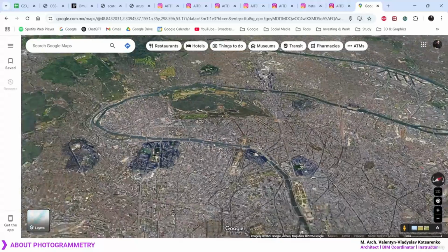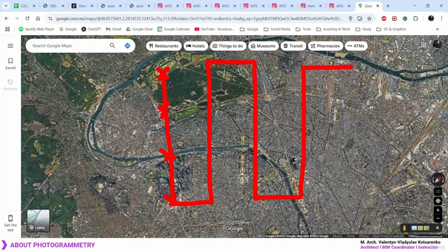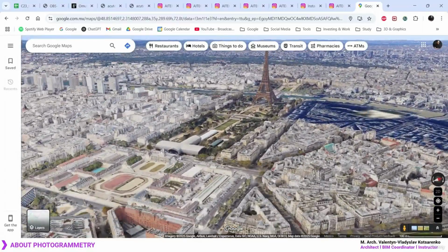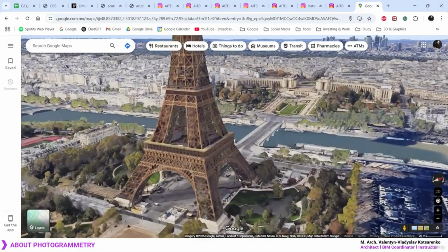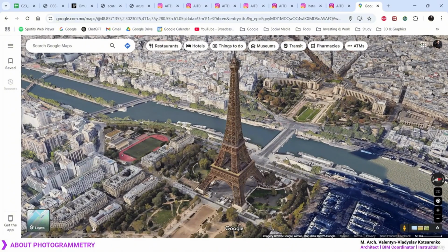So what's going to happen is that a plane is going to create a flyby, okay? It's going to use satellite photos and information created with the flyby of a plane in zigzag. It's going to take multiple photos, and then the photos are going to be interlocked with the software in order to create this type of model. So in long story short, you got multiple ways of creating photogrammetric models, pretty much based upon photos, except the scanners which already scan and generate the model directly.